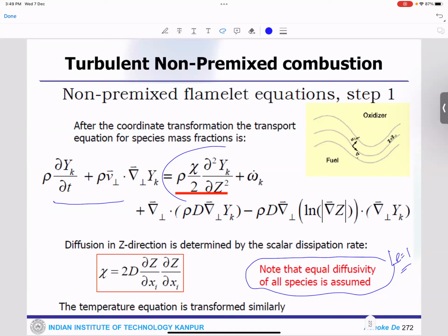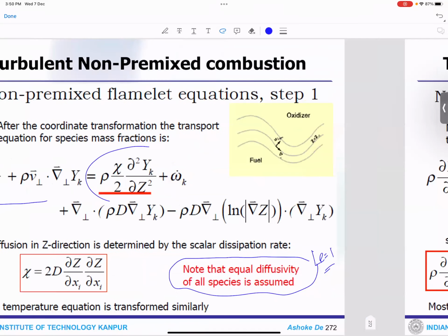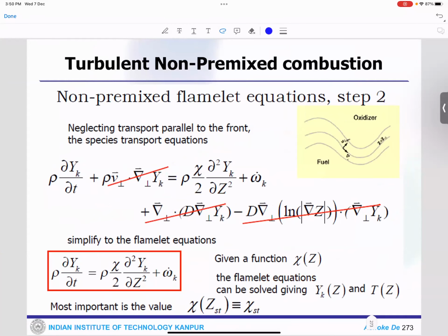One may think people have been studying hydrogen combustion for years, but this is where the challenge is. Capturing the flame structure under turbulent combustion, your Lewis number assumption may not be valid anymore. So all this calculation pattern and things like that are going to change. So this is how you derive.